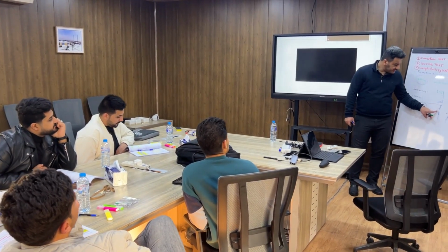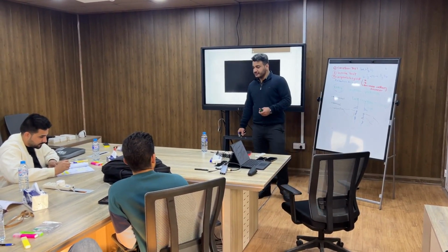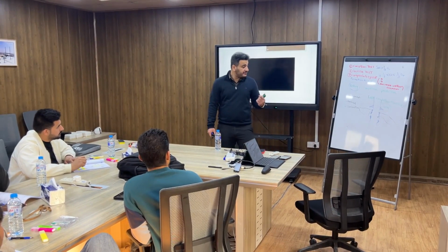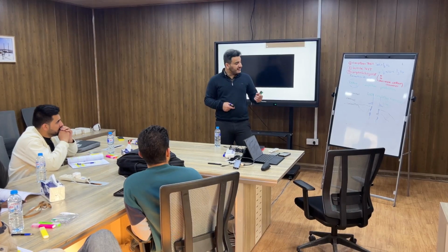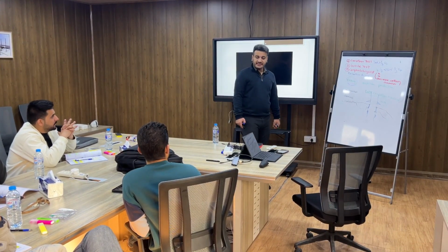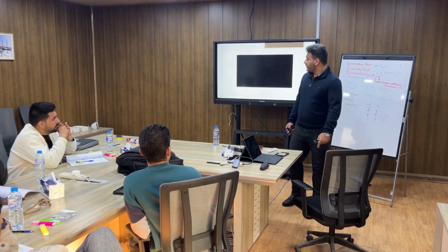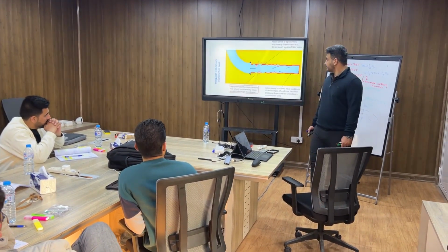So it creates a blockage at the interface to control the drilling fluid loss. But after the drilling, during the production or the workover operation, they easily remove the LCM by acid wash or back circulation. Let's view a video related to lost circulation material.